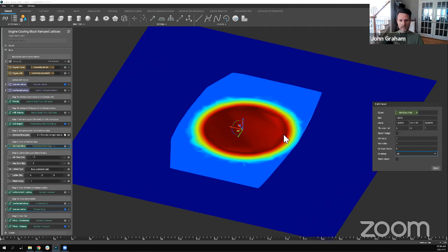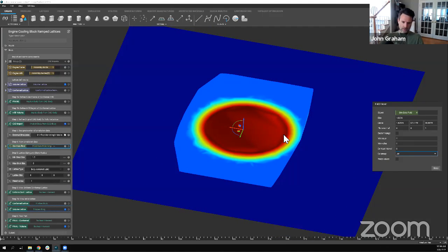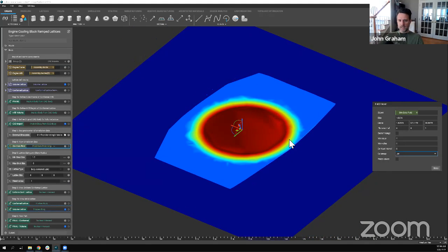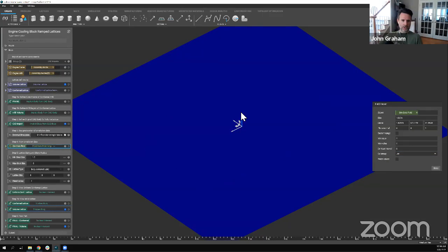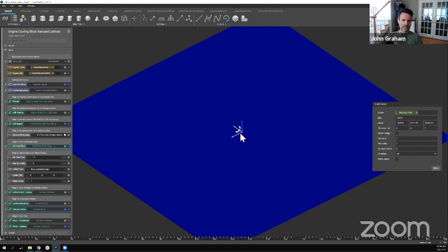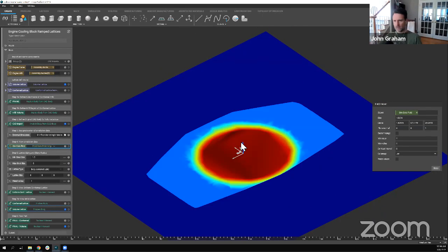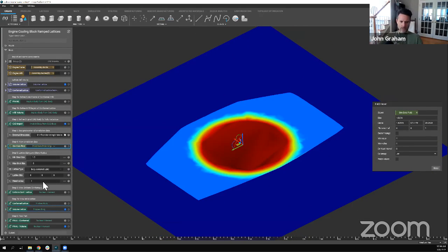If you were running a simulation on the combustion, on the heat transfer of this engine block, you would see a localization or a high temperature reading around the central axis, around the central perimeter of the bore, right? And so that's effectively what I'm showing right there. That's what the simulation data looks like coming in. This is just a cross section of it, so I can really go to any spot along the z-axis, in this case, and see what it looks like.